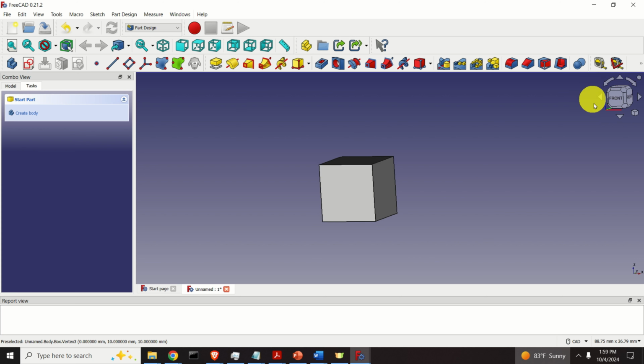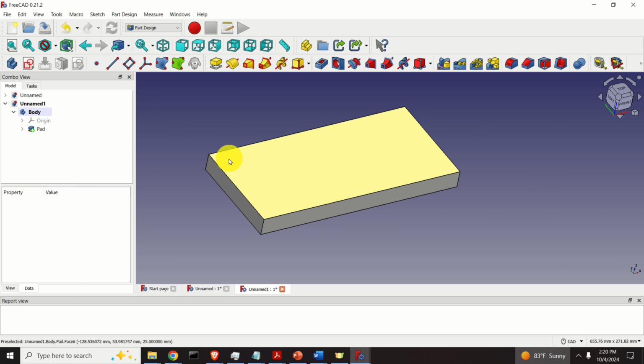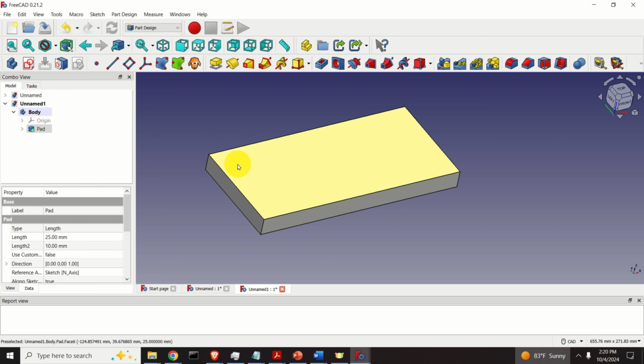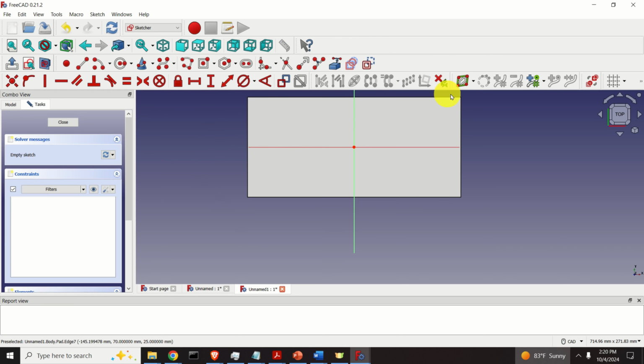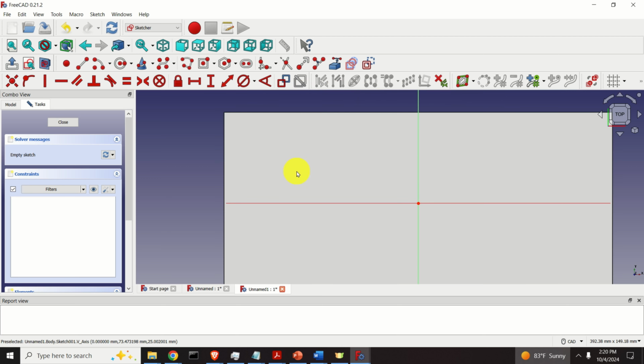The idea is to define circles in this top plane. Let's learn how to do that. Select the top plane and then click Sketch. This operation will create a sketch on this top plane. Over here we need to define 4 circles. Let's start with the first one. Click over here, then click somewhere over here and drag the mouse button and let's select, for example, 17.8 or 18. It doesn't matter. Later on we will precisely define the diameter and the radius. Okay, so here's our circle.